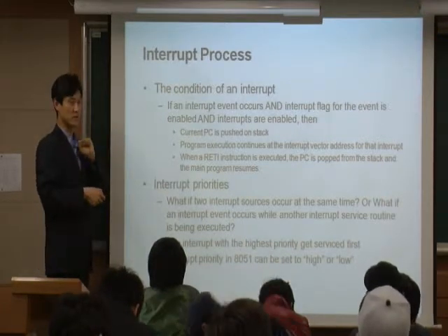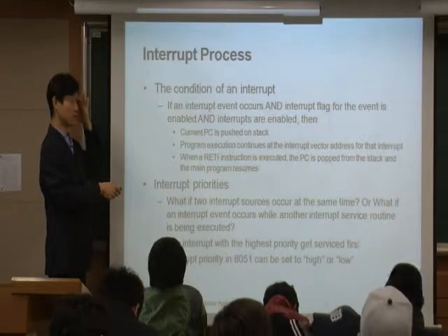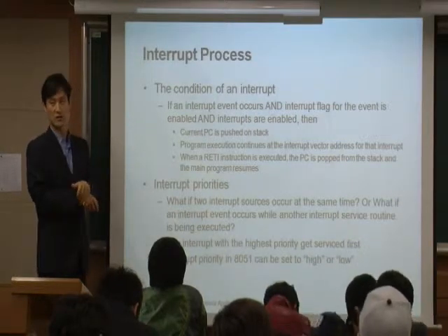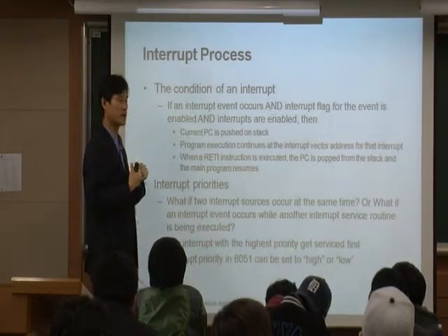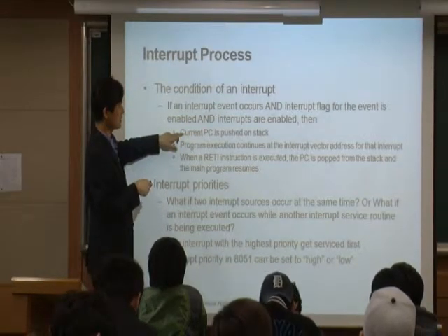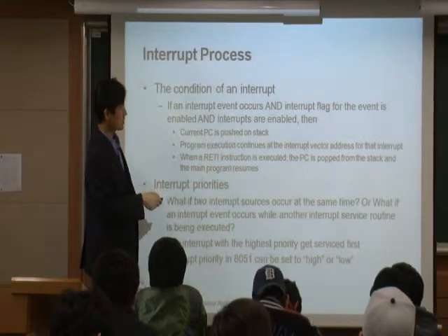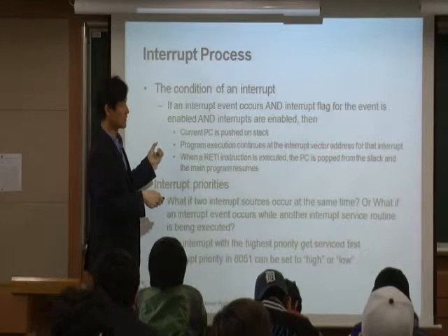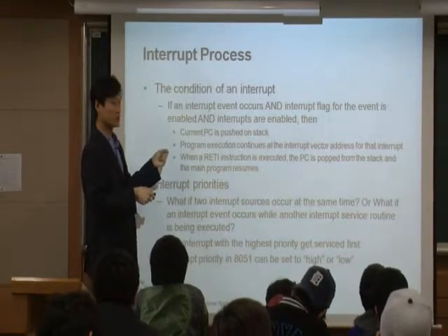When an interrupt comes, first of all, your current program counter is pushed to the stack, same as call instructions, because we need to come back later, right? So your current PC is pushed to the stack, and you jump to the interrupt vector first and find out where to jump.